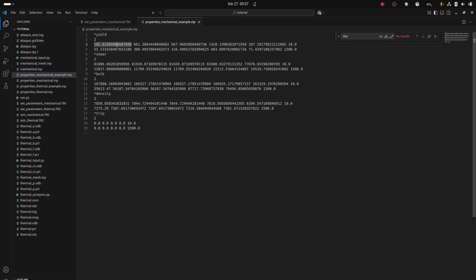What's different from the thermal input file is that in the thermal input file we specified basically for 2 phases. So we had the ferrite, pearlite, bainite, and martensite phase. We had 1 property because for thermal properties, these are all BCC phases, so they don't change that much. And we had a different property for the austenite. Here we have individual properties for all the phases.